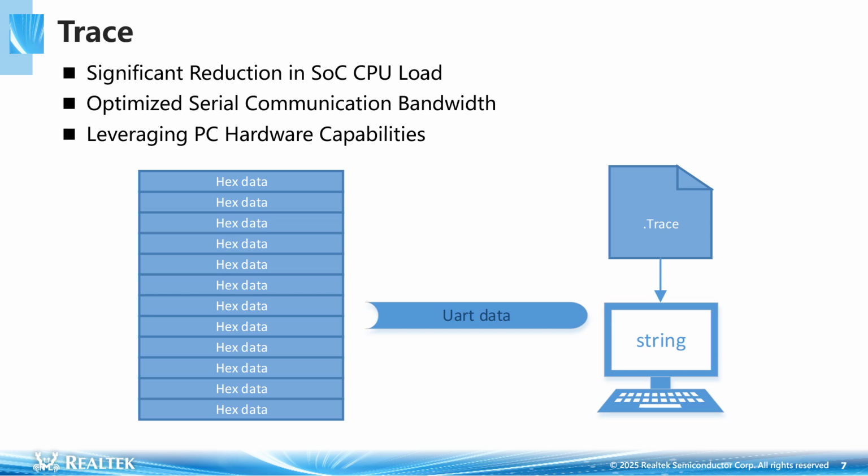1. Significant reduction in SoC CPU load. By delegating computationally intensive translation tasks, e.g., hex to string, to a PC, the SoC's CPU is freed from resource-heavy operations. This allows the SoC to prioritize time-critical tasks, e.g., sensor data processing, real-time control, and avoid performance bottlenecks.